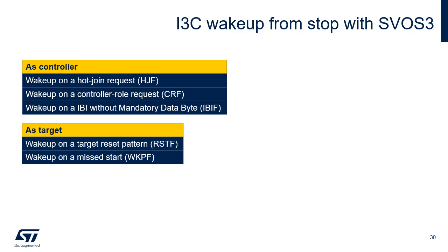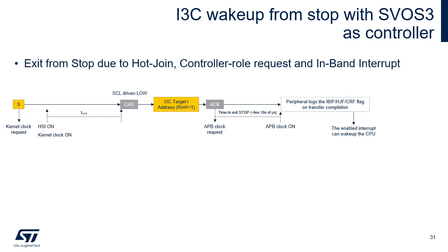A controller can wake up on an IBI without MDB, a hot join request, or a controller role request. A target can wake up on a target reset pattern or on a missed start, as explained in more detail in the next slides. When the peripheral acts as controller, before the product enters a low-power mode, the software must